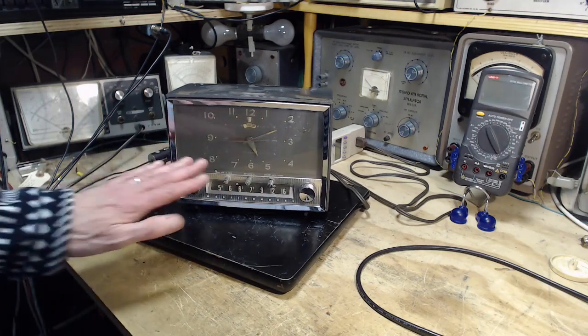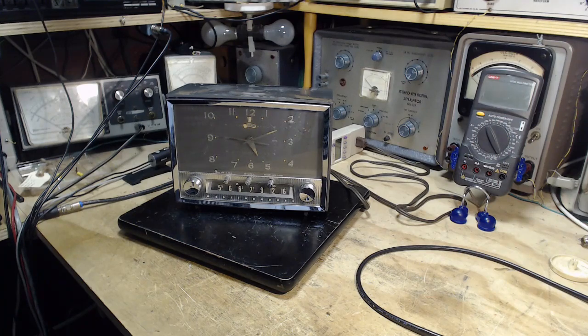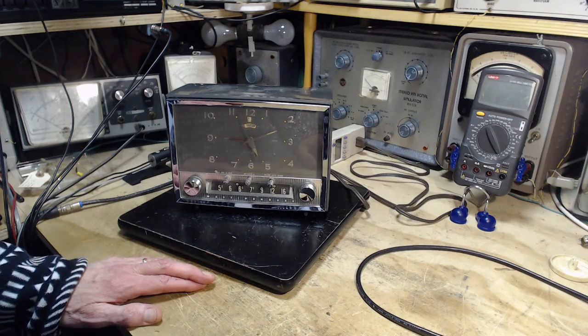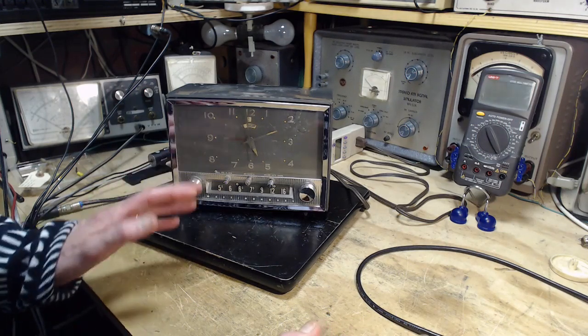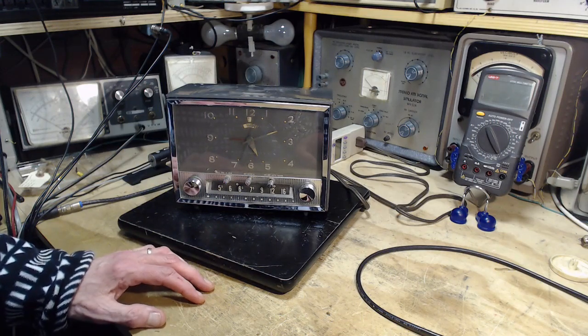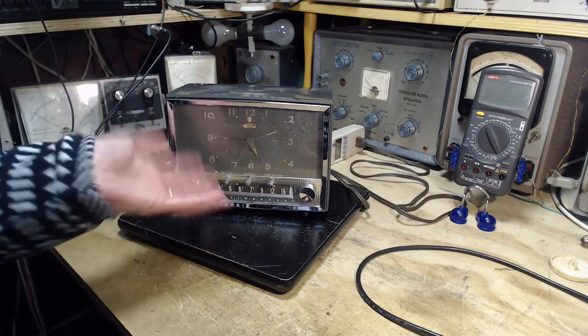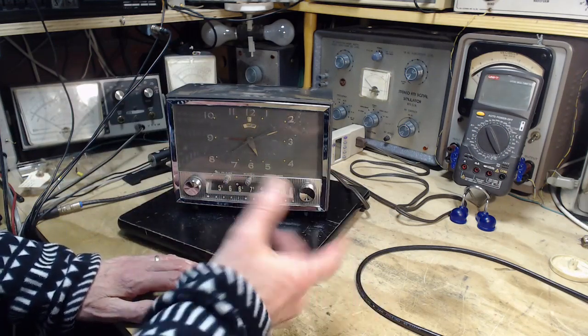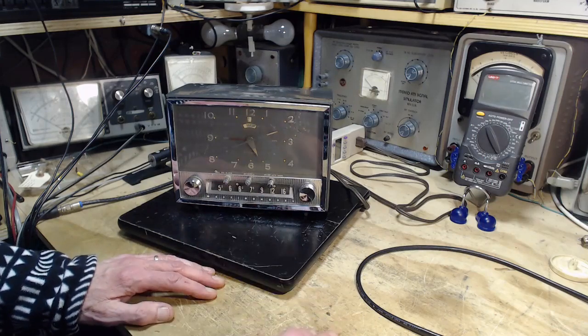So there's another effect I can hear here. Again, in a lot of shortwave radios, they have a feature called a beat frequency oscillator, and it's another oscillator. It's usually in the IF range, I believe. Maybe it could even be an audio oscillator, but I believe they oscillate in the IF range, and it injects another signal into the IF, one whose frequency you can move around.